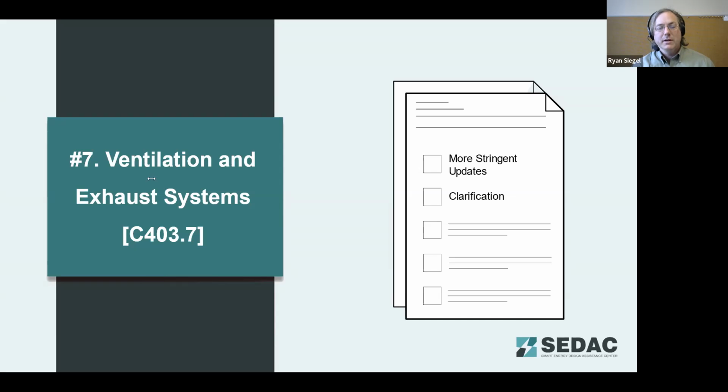Second question: why are VRF exempted from the economizer? It is the first one. Heat pumps are very efficient, so the economizer is of minimal benefit. Many VRF systems also are heat recovery, but not always. The second one would also make logical sense, but that may depend on the type of VRF system you pick. So it looks like most people picked up on this.